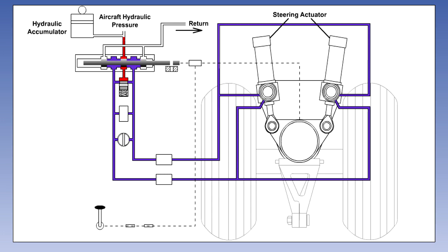There are two steering actuators which steer the nose gear. The restrictors in the pipelines between the steering actuators provide dampening for the steering operation and help to prevent nosewheel shimmy. As we mentioned, shimmy will be explained later on. The steering wheel or tiller is mechanically linked to the steering control valve. A follow-up linkage from the nose undercarriage gradually resets the control valve as the nosewheel turns.